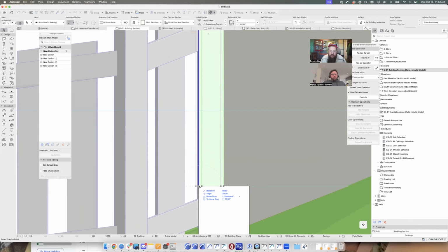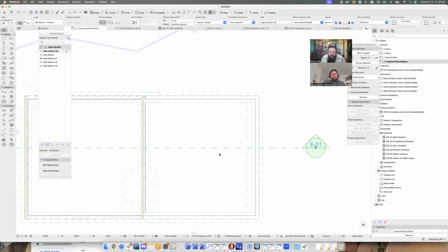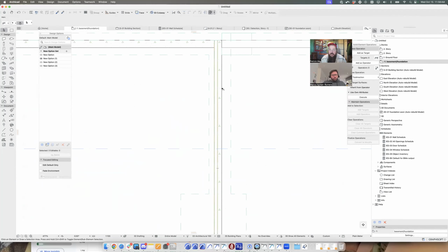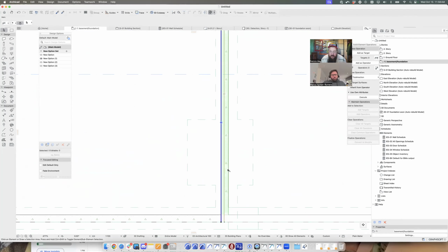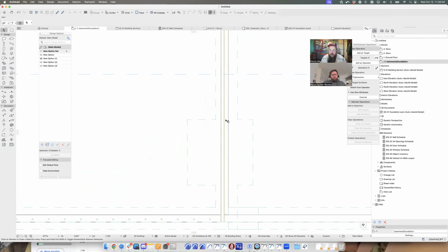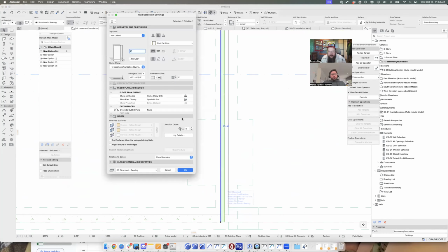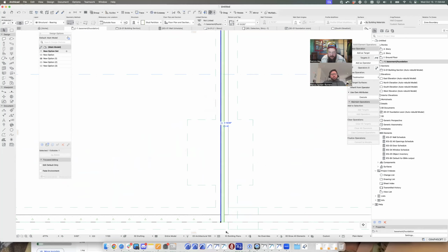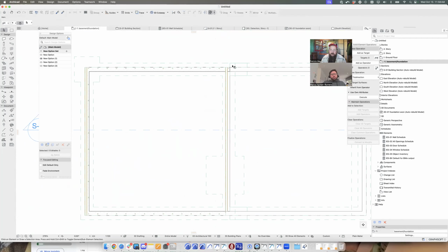I see. And then what does it look like on the floor plan? So it could look any number of ways that we needed to show it. This is going to show as the wall here. I could set this wall to show as outlines only, so that it shows as a stem wall behind, and then this shows as the pony wall above. I see. It looks like it's intersecting weird here with this wall, but if I go into the settings of this wall, I can probably bump that down, pull this into here, make sure that that's discontinuous.